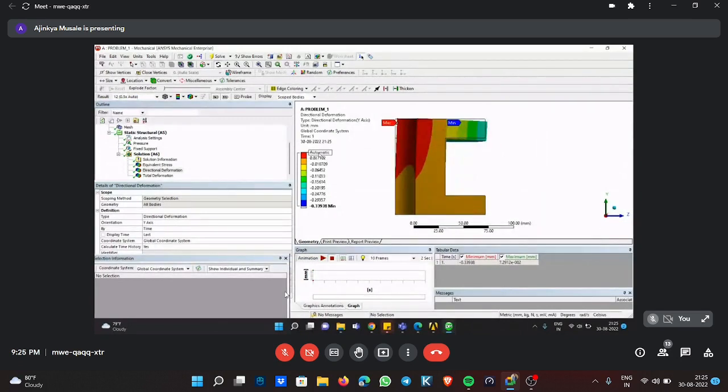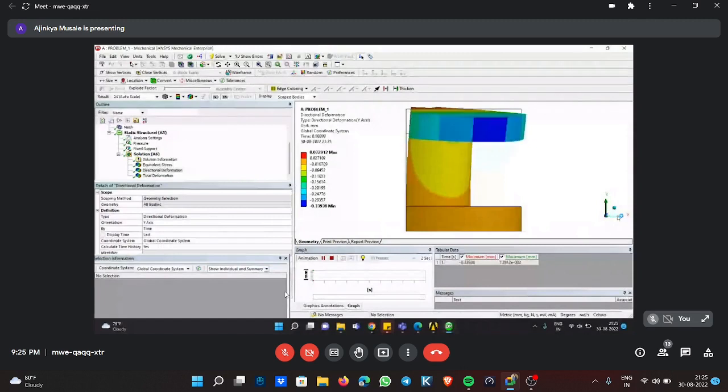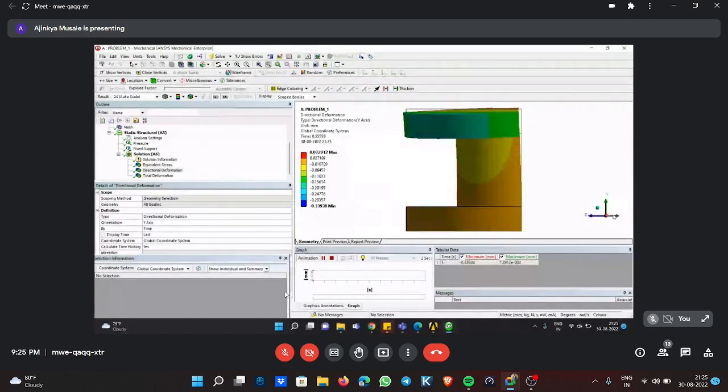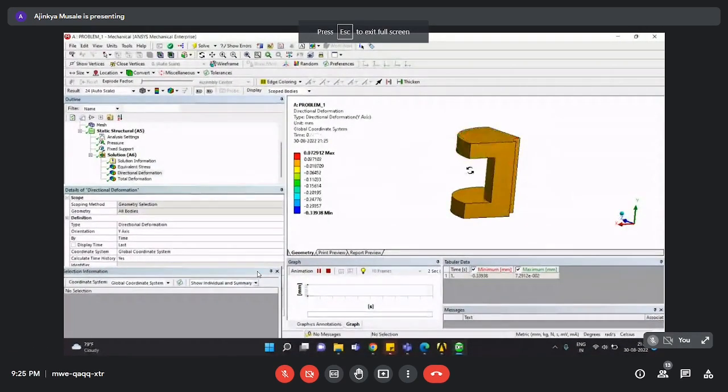So this deformation you can see is 0.07. You cannot even see it with your eyes. That's why I need this big factor, like 24 times actual, right? And just see the exaggerated view, how it is behaving. Maybe you can see it in a different direction. From here you can get a glance, you can come to know how my body is deforming or how it is behaving under this kind of load. Have you ever imagined, when you sit on any stool, this stool behaves in such a way.